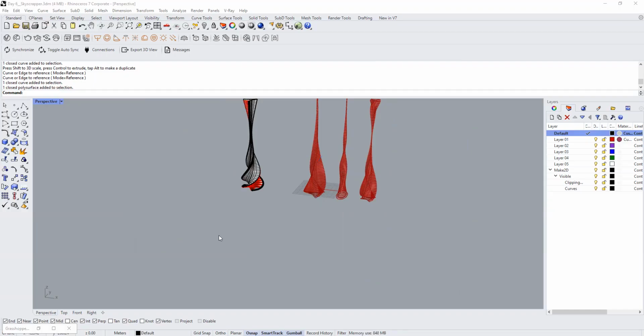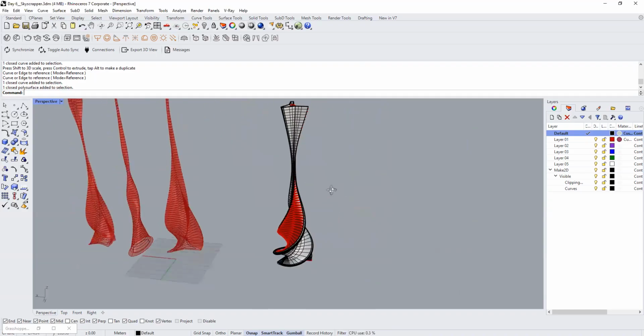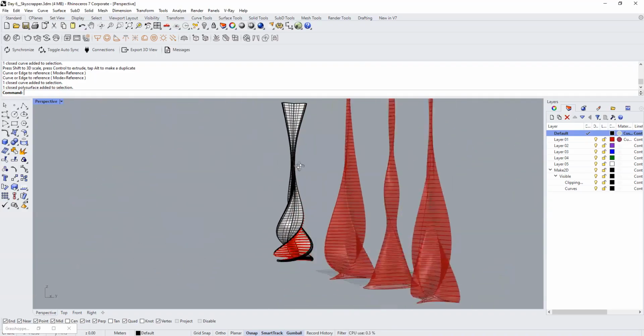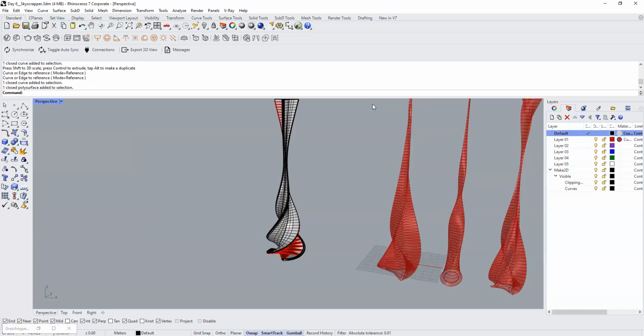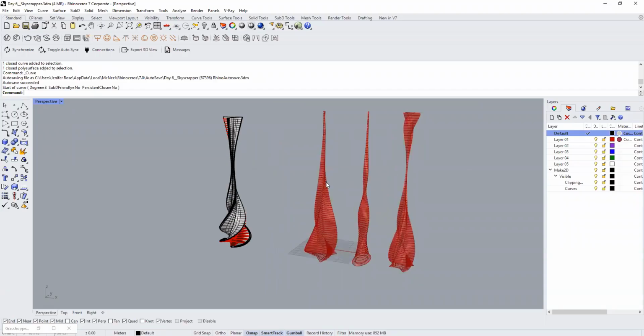Okay, but don't you think it would be very tricky to create a curve from scratch that follows this twisted profile of the surface? Any easy way to get a curve on the surface? Extract the isocurve, maybe. Exactly, you would extract an isocurve. And when you extract that isocurve, you can directly use that as the cutting curve for splitting.